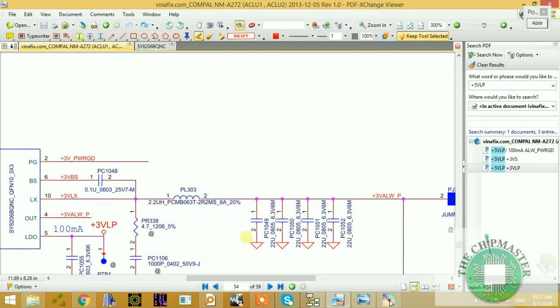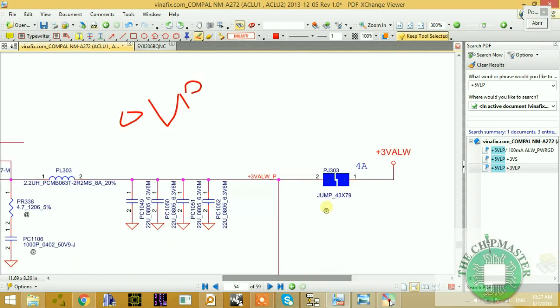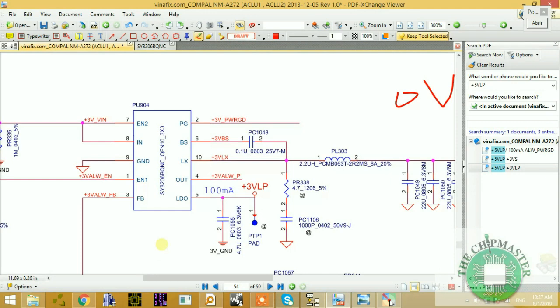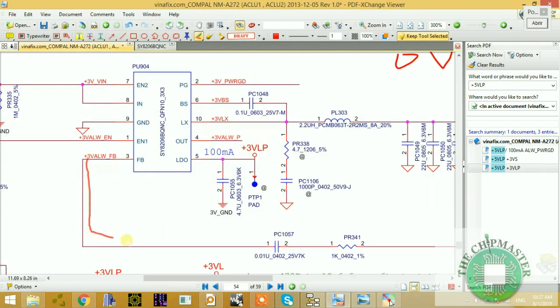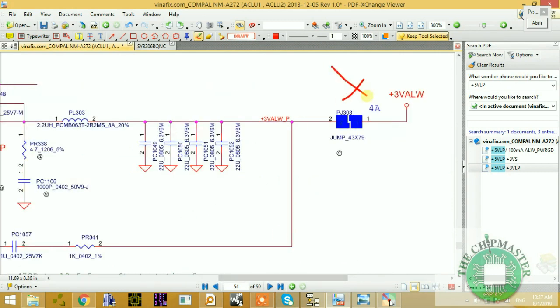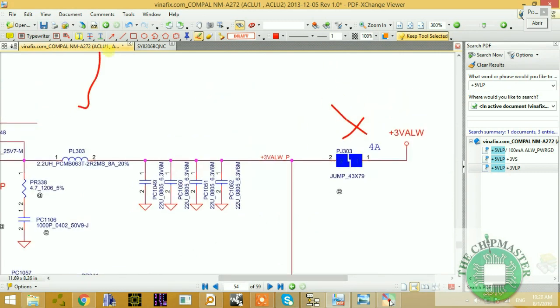If you have an over voltage, if it's OVP, suppose this chip is outputting too much voltage, then it will report back to the feedback circuit, right? As you can see, indicating that there is an over voltage protection, and it will shut off the output also. So on the oscilloscope, you'll get a nice rising edge like this, right, or something like this.